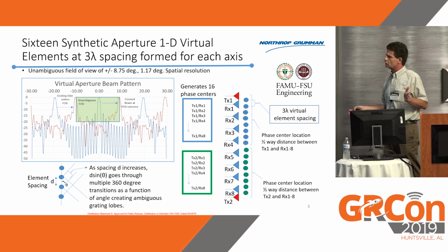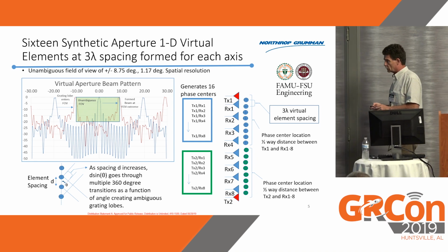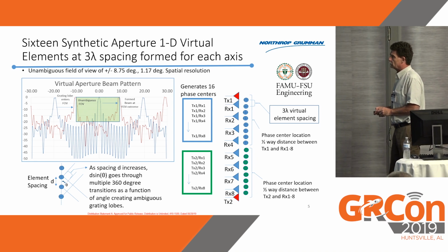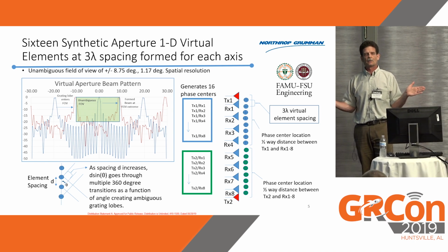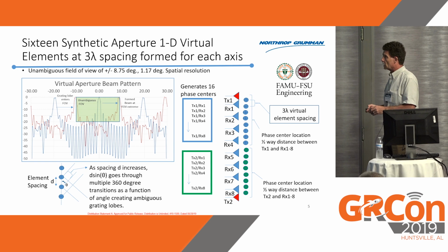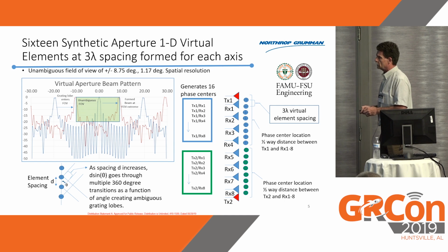So it's analogous to aliasing in the time domain. In the spatial domain, you get what are known as grating lobes in your real space domain. So it limits how much you can then scan and digitally beamform. These blue traces show the separation, and I'll tell you why we have to go with that separation. You get grating lobes here, but at boresight at 0 degrees, you're fine.